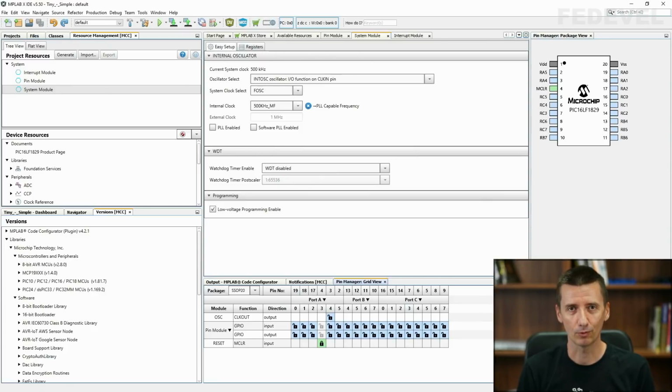Sometimes, if you have to do it this way, it can be a lot of work. It can be super time consuming. Sometimes it's very difficult to verify if you set some of the settings correctly or if it's wrong, or sometimes it just doesn't work, and you find out why it doesn't work, and it's because you forgot to set one bit somewhere in the register of the microcontroller. You can spend days, sometimes even weeks, trying to set microcontroller registers correctly.